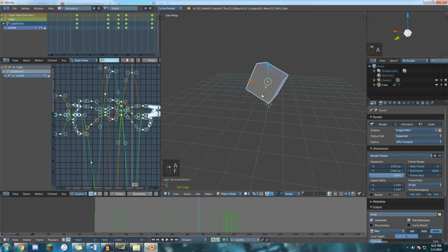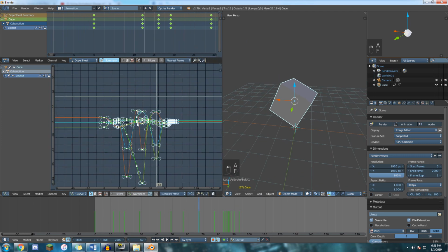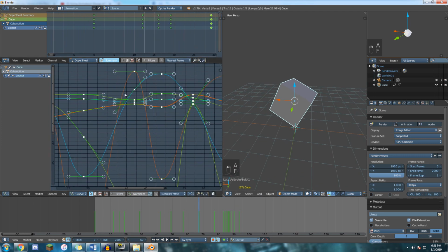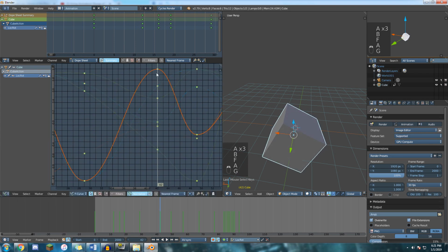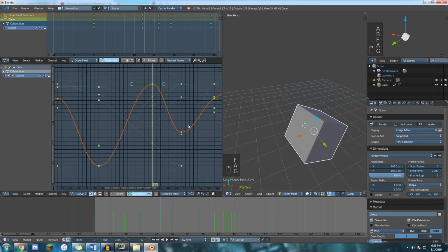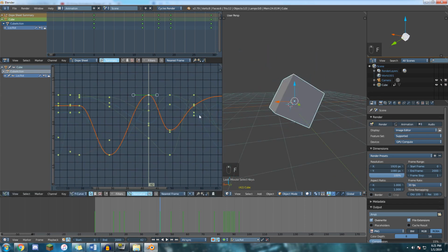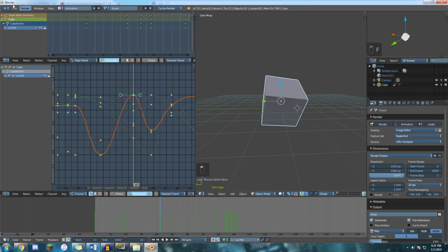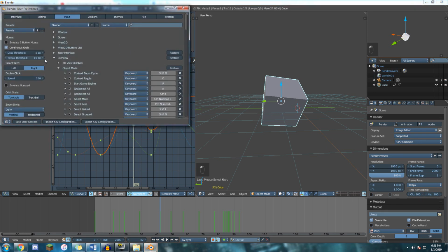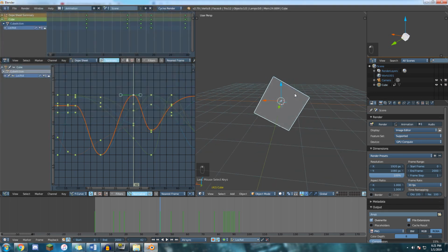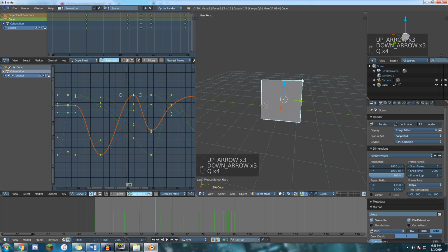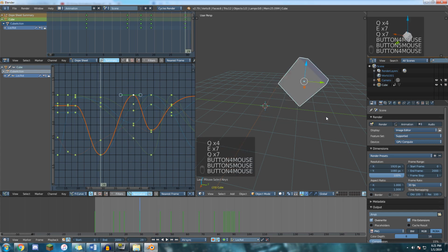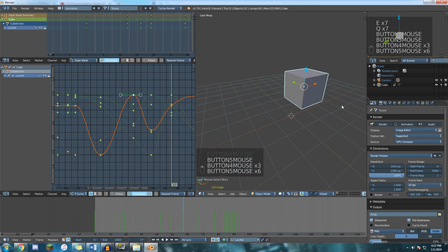As my final advice, a lot of it is just learning the Dopesheet and graph editor, being able to quickly go in here and polish things up, having it set to normalize if you want to push everything together and see everything. And it's just a matter of using it, practicing it, finding out what works best for you. These tips might not be what's best for you, which is why I mentioned the hotkey one, and I mentioned doing whatever hotkeys you find yourself using a lot. I use the arrow key stuff a lot, so for me it made sense having my Q and E be frames and having my mouse 4 and 5 be the keyframes.